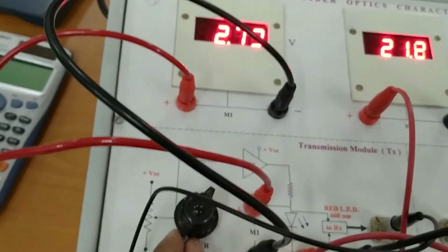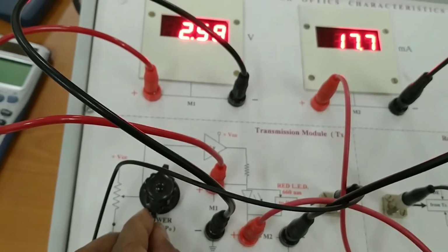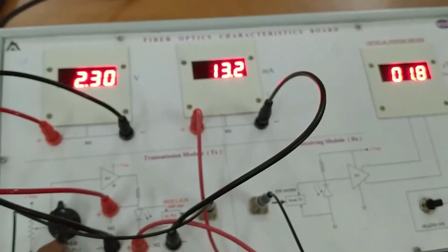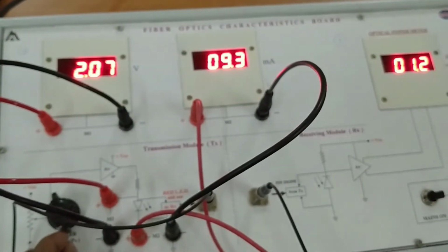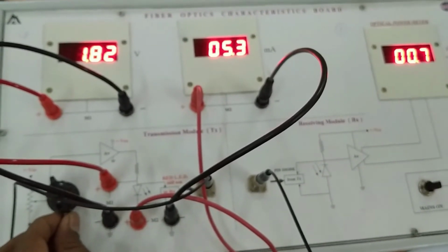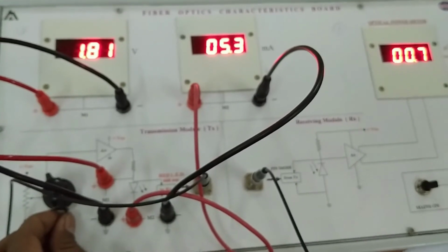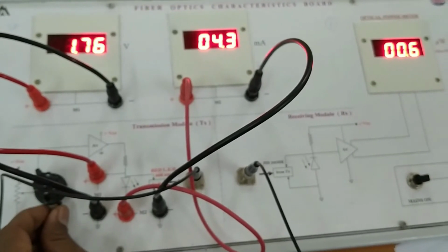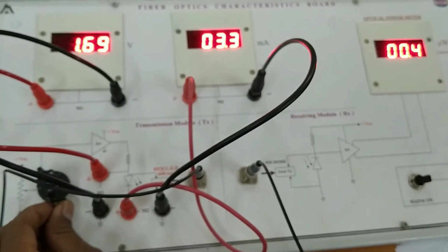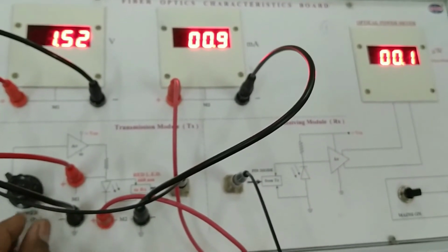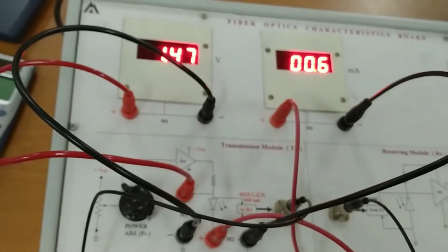Move on to this. I am now adjusting the value of the voltage. If you see, the current is also changing, the power is also changing. If I keep a very small input voltage, the optical power almost becomes 0. Therefore, I am going backwards. Initially at the higher value, I change this slowly, and the power is around 0.5, 0.2, 0.1. I am taking 0.1. Now I will change the voltage and measure it.